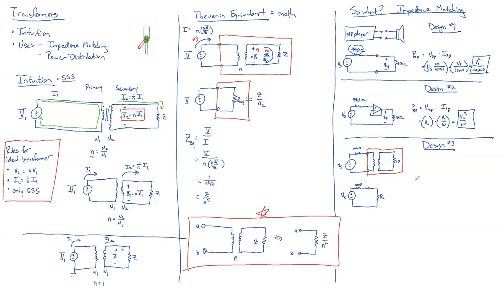Remember, the power across your load is equal to the current through the load times the voltage across the load. When we made that resistor 0, it had no voltage across it, so the power dissipated was 0. When we make this resistor infinite, how much power will there be? Think about this equation. Yes, all the voltage will be there, but what will happen to the current if we make the resistance infinite? 0, no current. And so once again, there's no power dissipated.